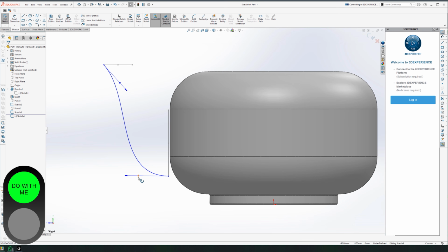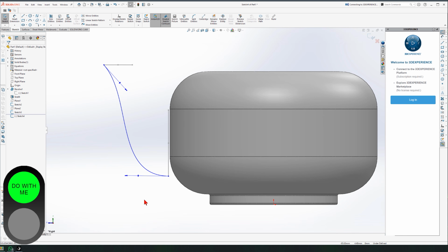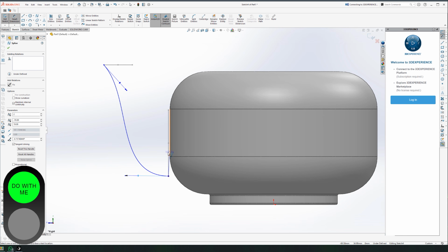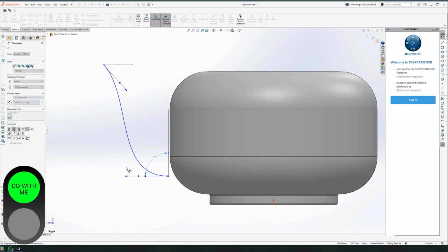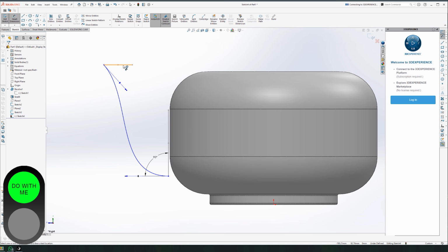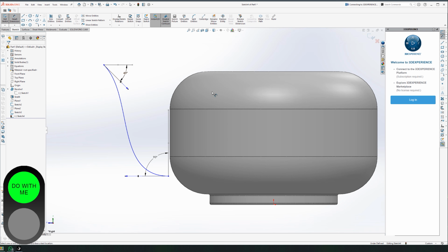So I'm going to click on this diamond just like you do. Or maybe select this and select this line and give it 90 degrees. And for this one, select our profile line, which can be used as a reference, and select the diamond and give it a 45 degree angle. That's it. We're not going to change anything else. And we would rebuild our sketch.